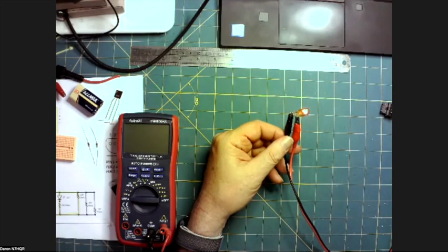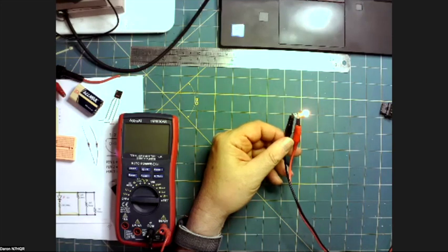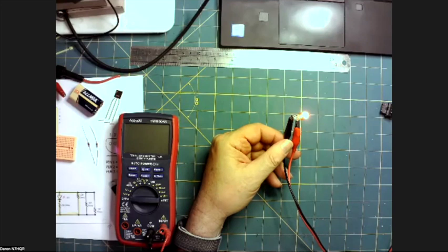So it'd be 0.166 times 6 volts would equal 1 watt. Okay, crank it up to 2. We can see it's brighter. Well, there's 2 watts at 215 milliamps.